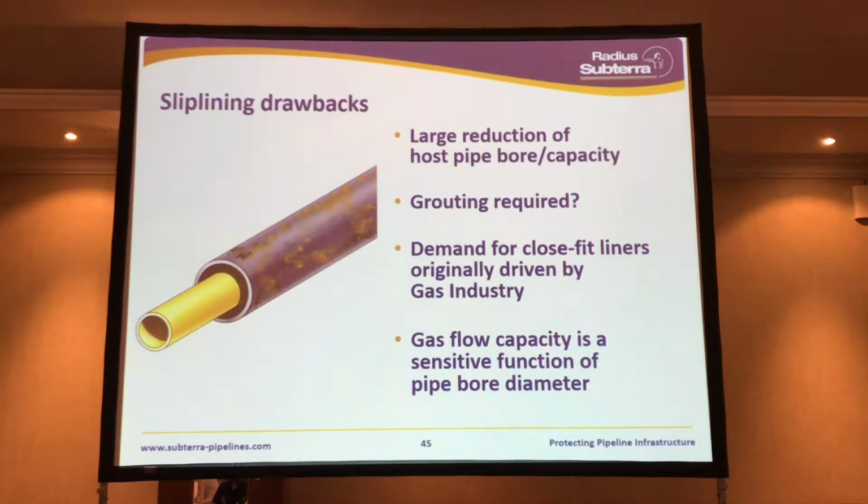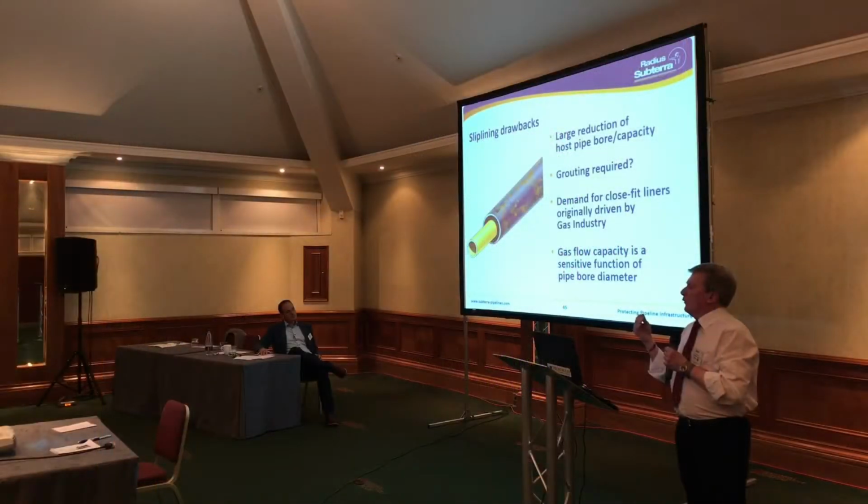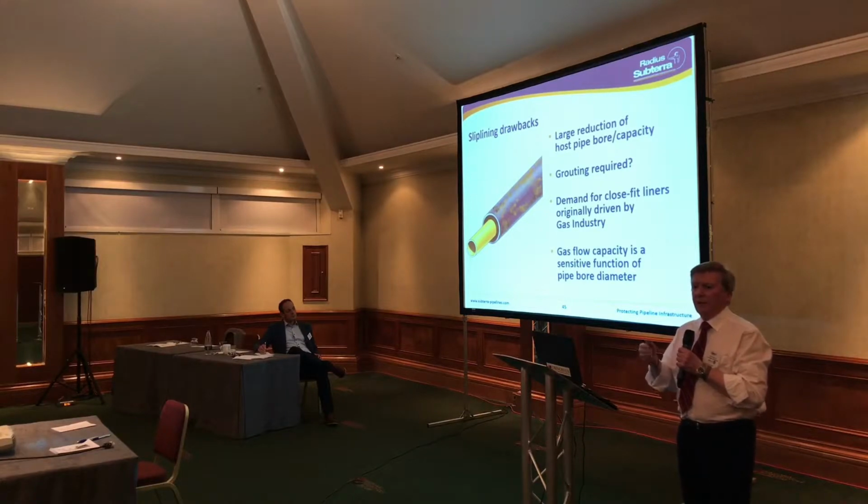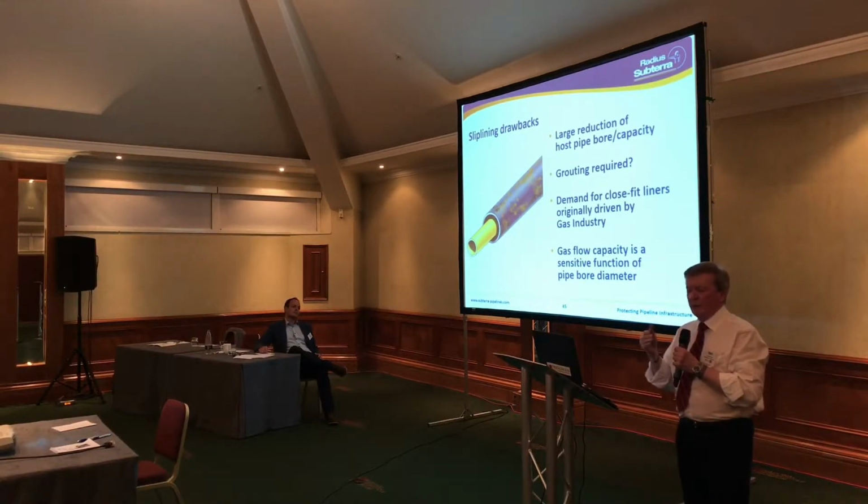The reason that the close-fit lining technologies were developed was really on the back of the gas industry. Gas flow, much more so than water, is a very sensitive function of the cross-section diameter of the pipeline, and it's more than the square of the diameter.